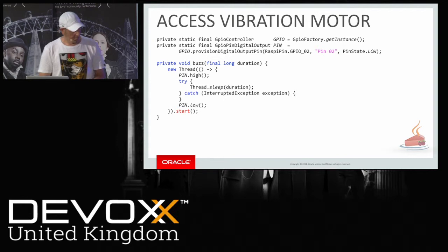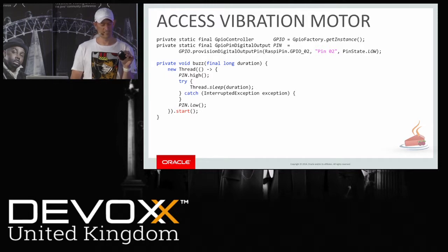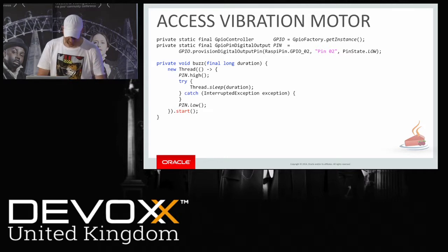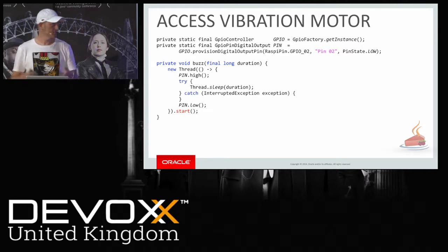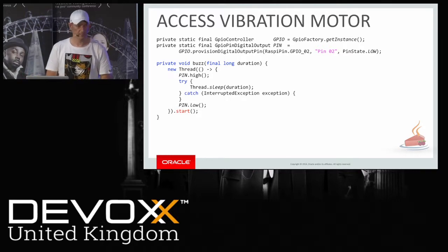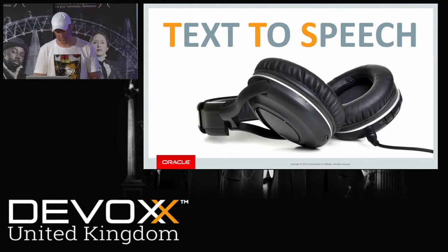It's not hard. The bigger problem was because it's vibrating and the GPS sensor is very sensitive to vibration. It's not a good idea to put that close to the GPS sensor. So I had to put it here somewhere and then try to separate it so that the vibration is not too hard on the GPS sensor. And these are all the problems. But you see the code is a piece of cake. For programmers, that's not really a big deal. That was a good one.